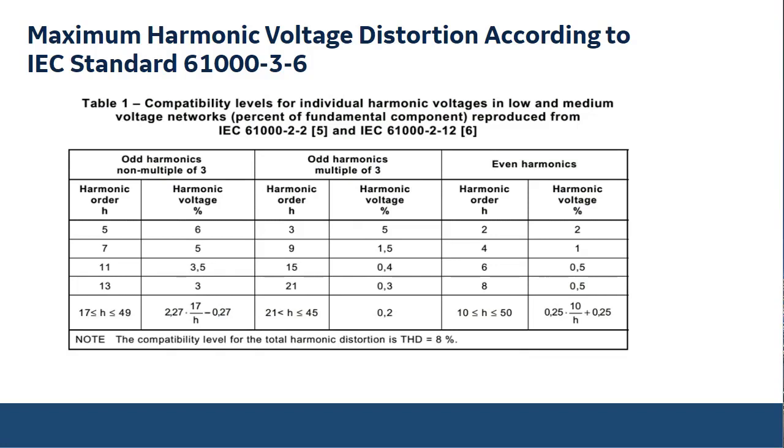And then this is our best guess if we cannot make any measurements or do simulations or something like that. Then, for example, we can use this dimensioning, quite safe for detuned capacitor banks. So if you don't know anything, we can quite safely say that we choose from here, let's say 6% of fifth and 5% of seventh, and then perhaps we typically put like 0.5% of third also in there, and then that is our spectrum.